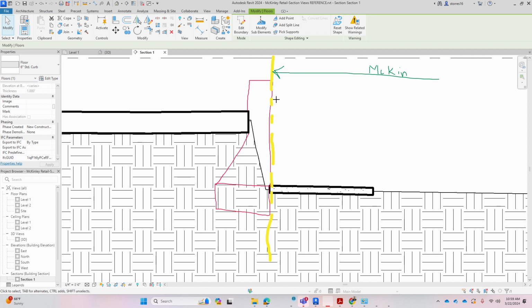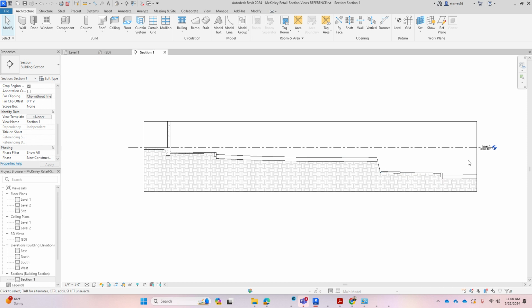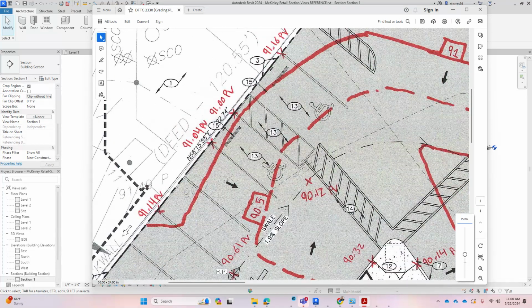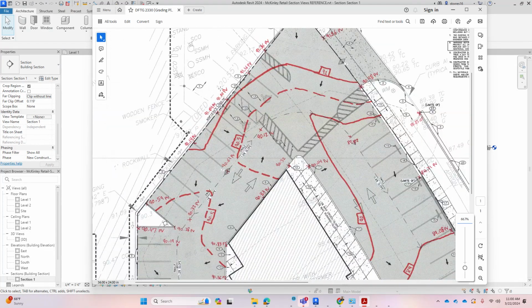But a lot of students never put this property line and this note, but it is very important to show where that right of way is in reference to our section view. So again, make sure you put that in and label it accordingly, in this case in particular. This is the right of way, this is private property, and you're going to see that in different sides of the view. So you're going to see that on the front view in here. You're going to see a property line over here, so you make sure you draw the property line where it exists on that section view.